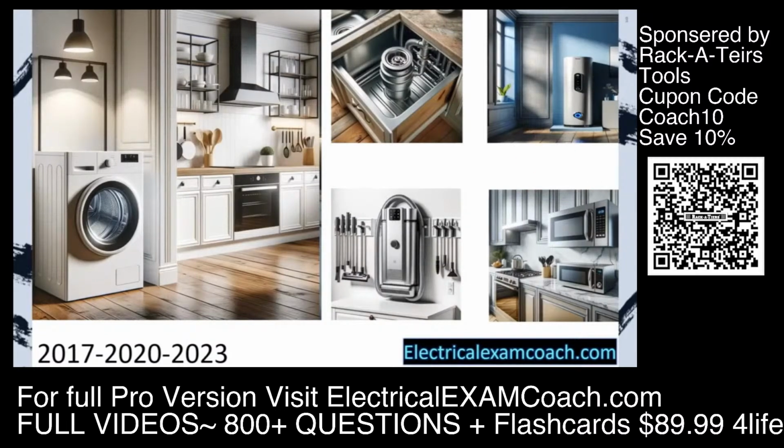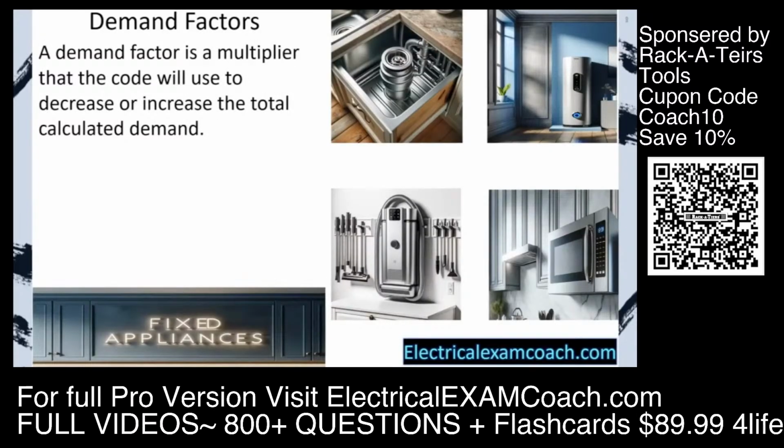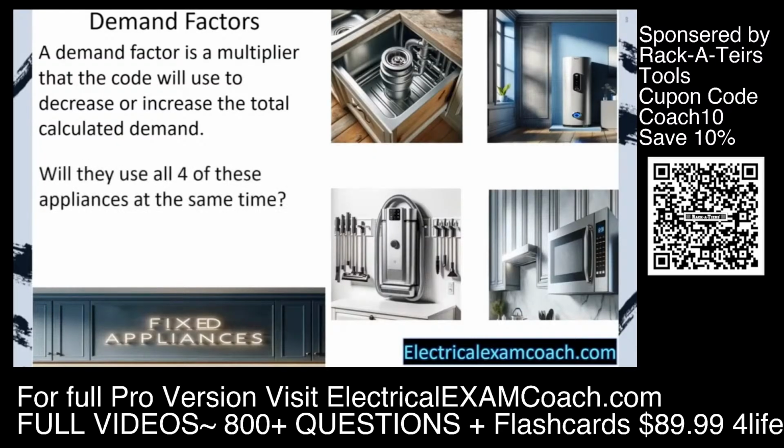Let's get to it. Before we dive into the calculations, let's learn about demand factors. We're going to be using them for the rest of the program. A demand factor is a multiplier that the code will use to decrease or increase the total calculated demand. The question is, will they use all 4 of these appliances at the same time? And the answer is no. So the code makers have made it so we can reduce the overall demand. Instead of just counting them watt for watt, they've made some multipliers that allows us to reduce the demand that we calculate.